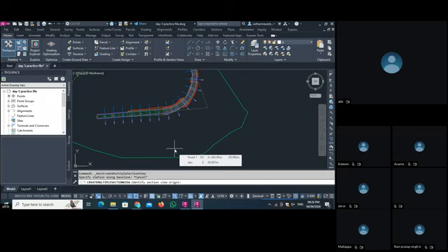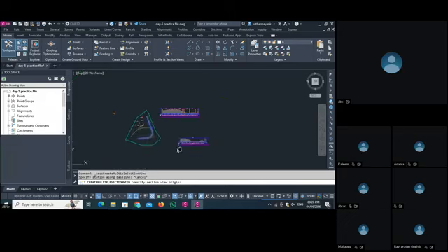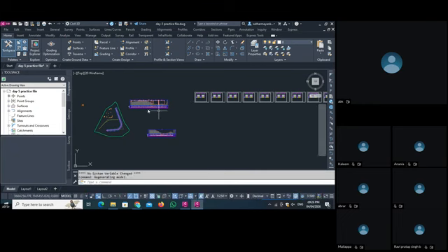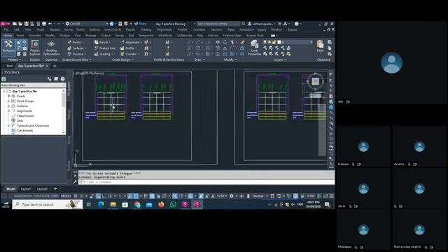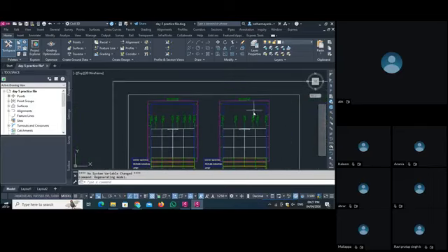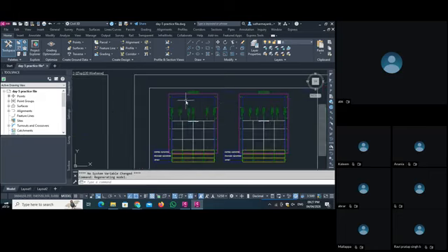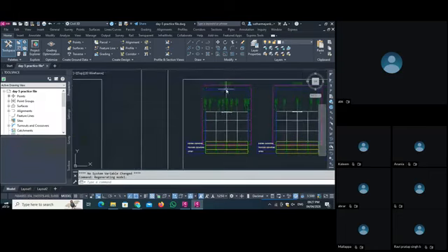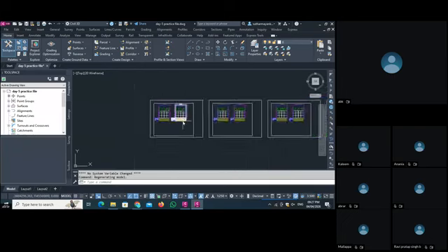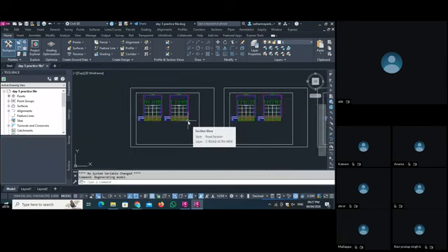As I select the create section view, you can see the identify a section view origin. So I have to click here on the screen somewhere. As I select here, it will take time, and see, it will create our section view. See, this is our old station 0, then the 20-meter of sample line, then 40-meter, every 20-meter of center line it will create. If I set that draft menu, then all our groups come in one sheet. Okay, but I choose this because you understand properly all the things.